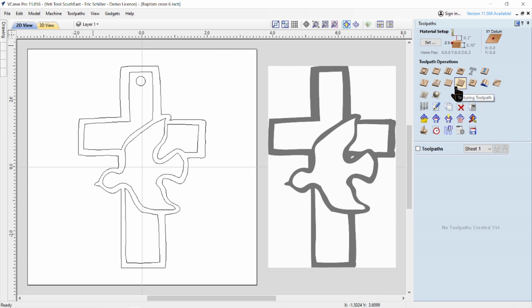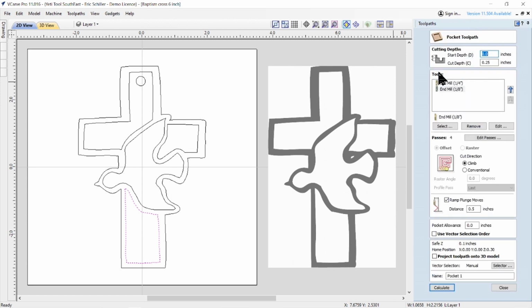So on the toolpathing, I would first take care of the hole that's going to go all the way through. Then I would pocket this and this and this and this, and then cut the profile. So let's go ahead and do that. I'm going to do a pocket command because remember we did a larger hole than our tool was, and I'm going to cut all the way through. So I'm going to say T for the thickness of material plus 0.020 equal.